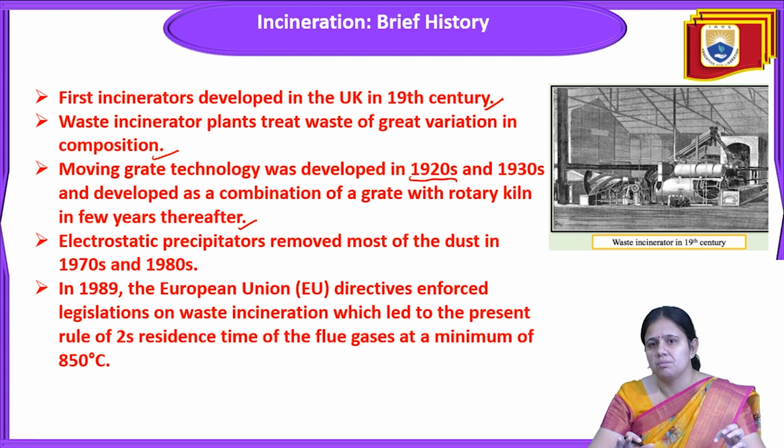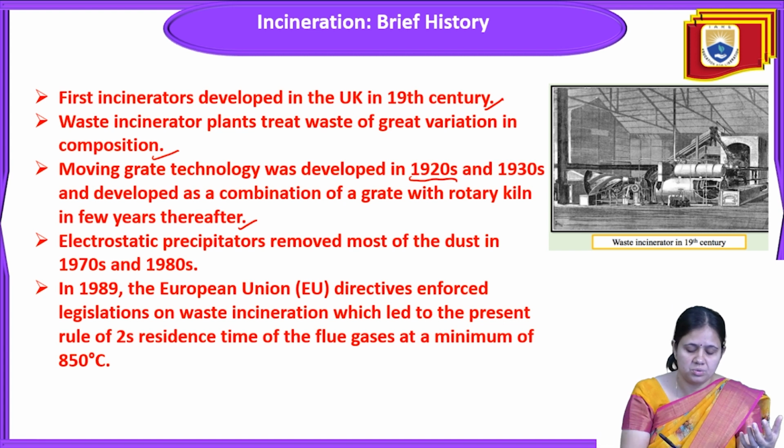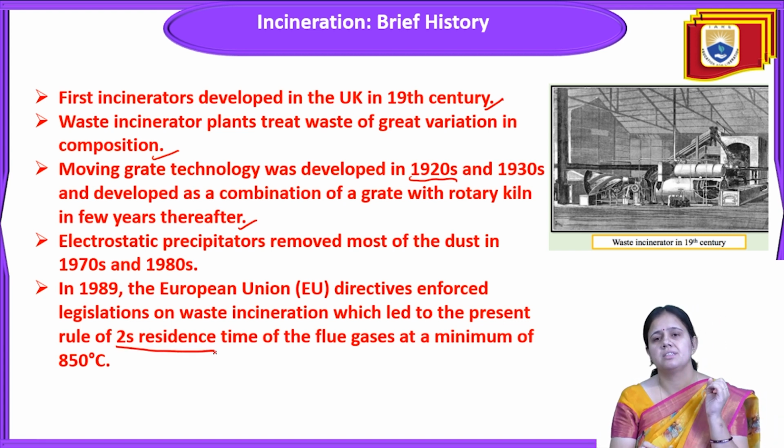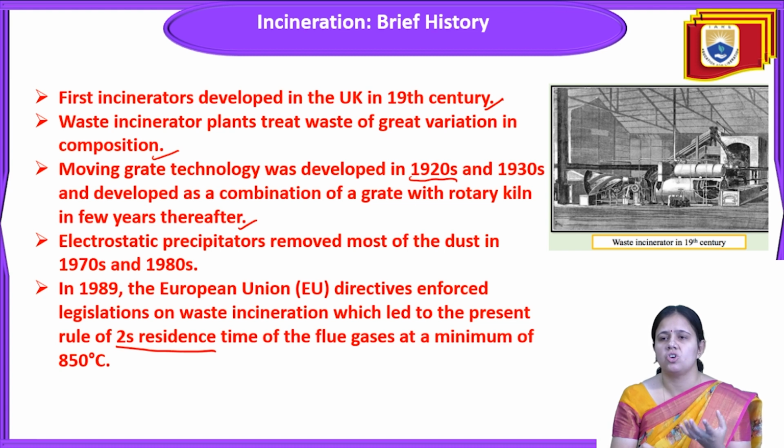In 1989, the European Union directive enforced legislation on waste incineration that led to the present rule of a 2 second residence time. That means they made a rule for a 2 second residence time of the flue gases, at a minimum temperature of 850 degrees Celsius. The flue gas should remain inside the incinerator chamber for 2 seconds only. So the residence time of this incinerator is 2 seconds only.